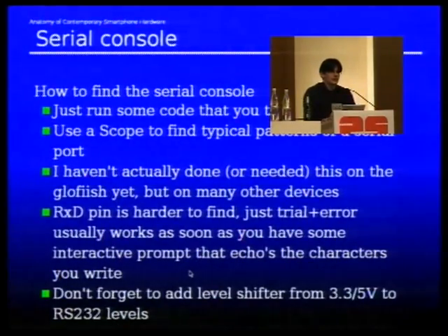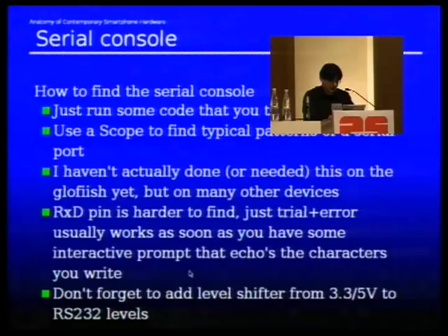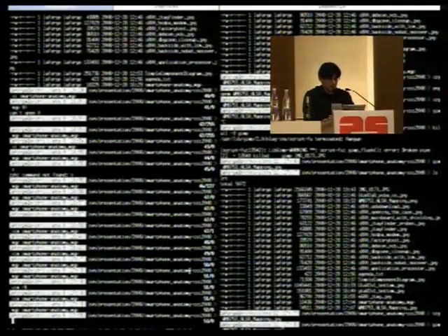Serial console is another useful thing. I mean, anyone who's ever dealt with like OpenWRT or similar projects, it's always useful if you have the serial console to the device in question, so you can, well, see what kind of debug outputs the developers left in the final shipping firmware image, and as well to see if there's any way how you can interact with the device. So Linux-based devices or Unix-based devices, I would say in general, in quotes, including like BSDs or VxWorks or whatnot. They typically have some kind of command line interface or console or whatever on the serial port.